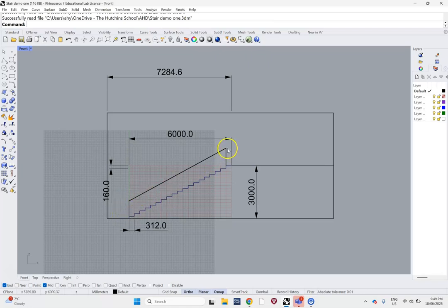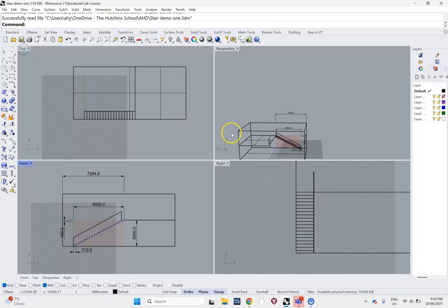These do represent handrails, which I've got at around 950 to 1,000 millimeters in height. You should always have handrails on the external side of your stairs, or that could be a glass panel with some writing on top. There's got to be some sort of safety rail here.